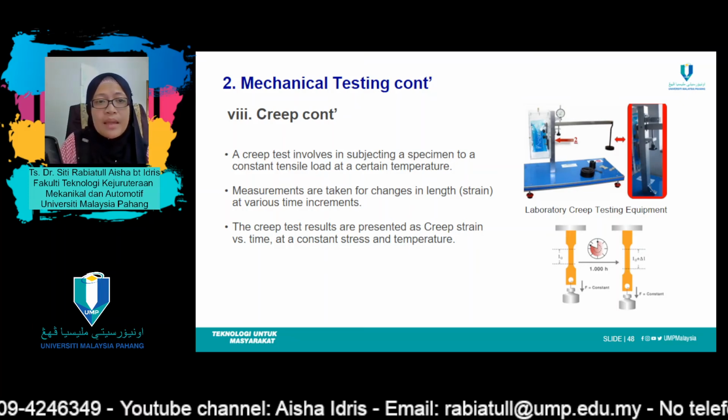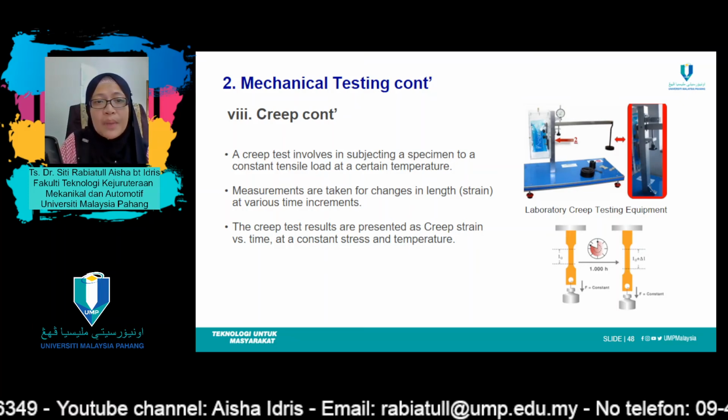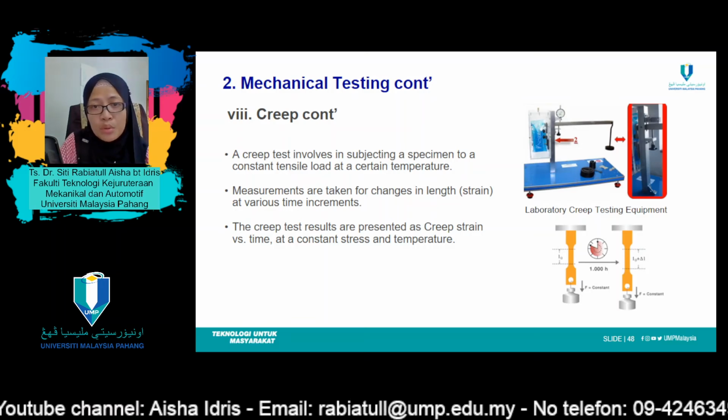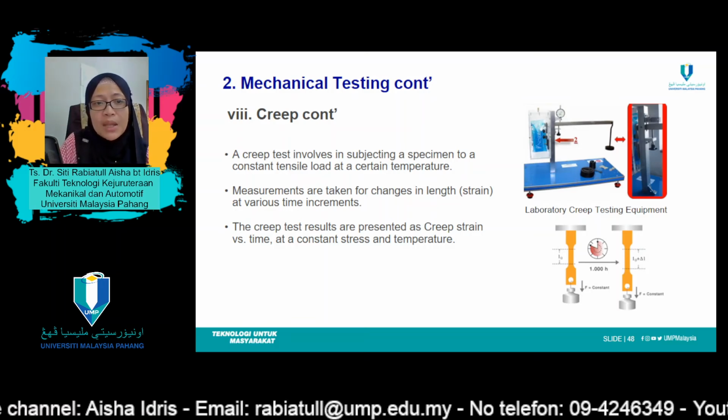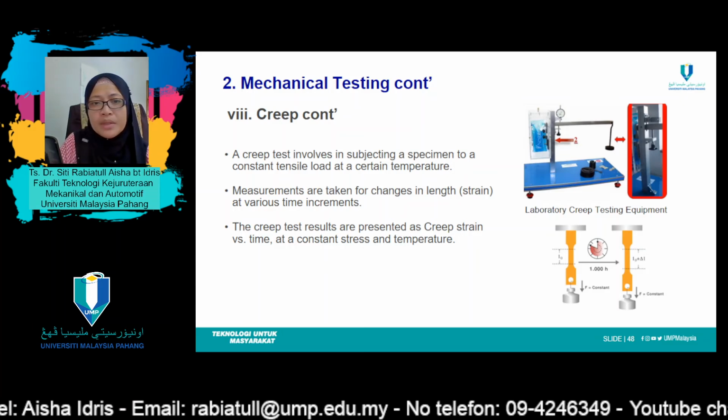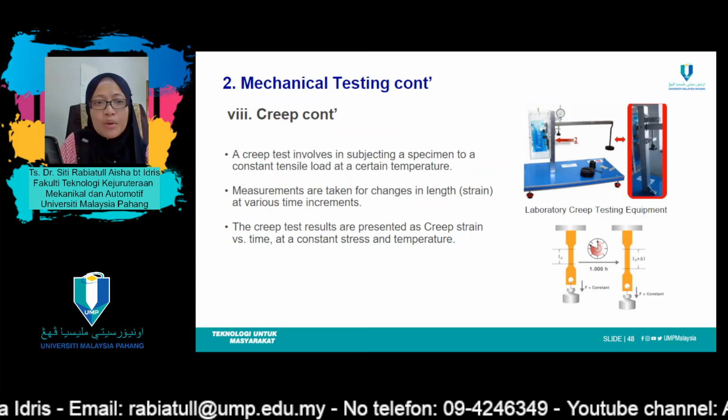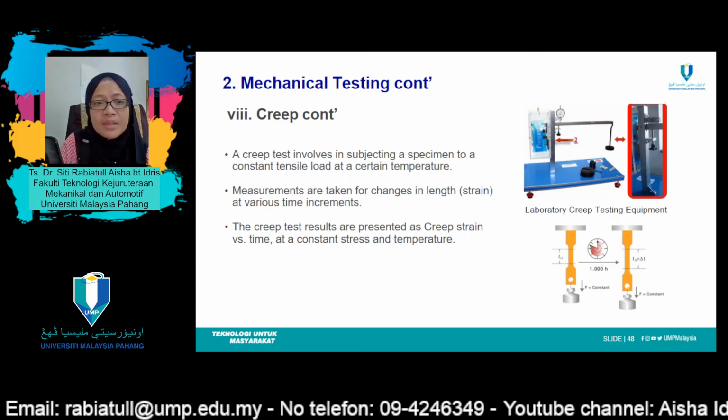A typical creep test consists of subjecting a specimen to a constant load or stress while maintaining the temperature constant. Deformation or strain is measured and plotted as a function of elapsed time.